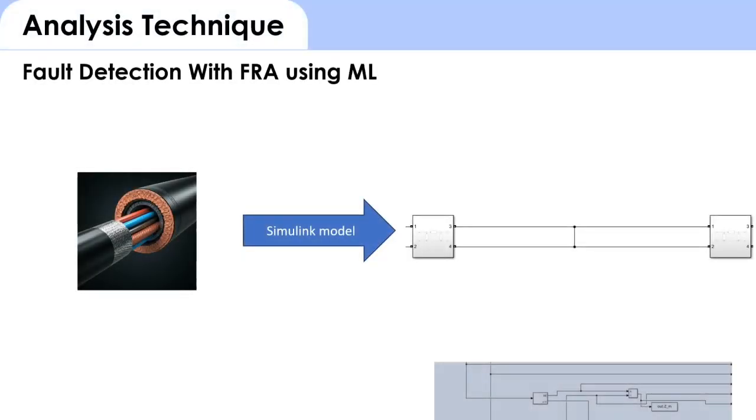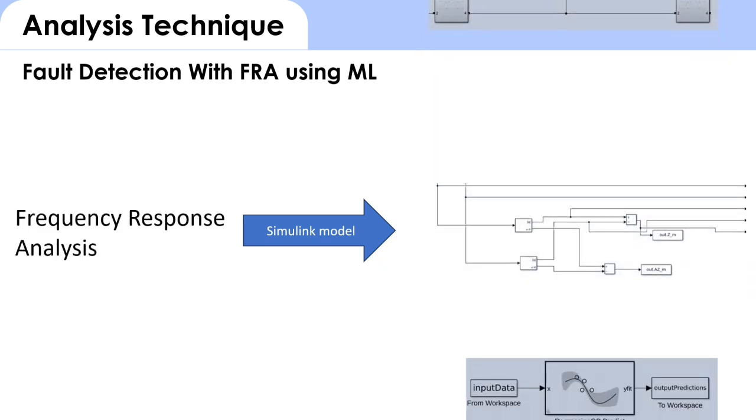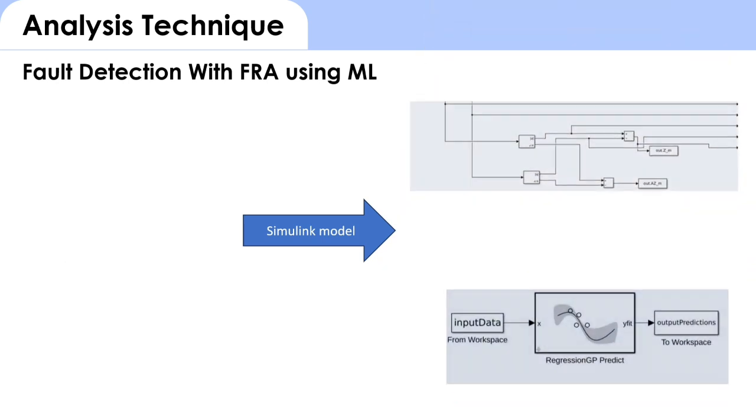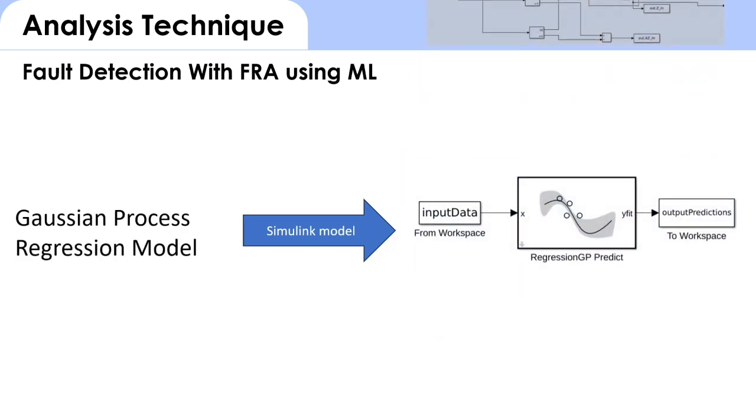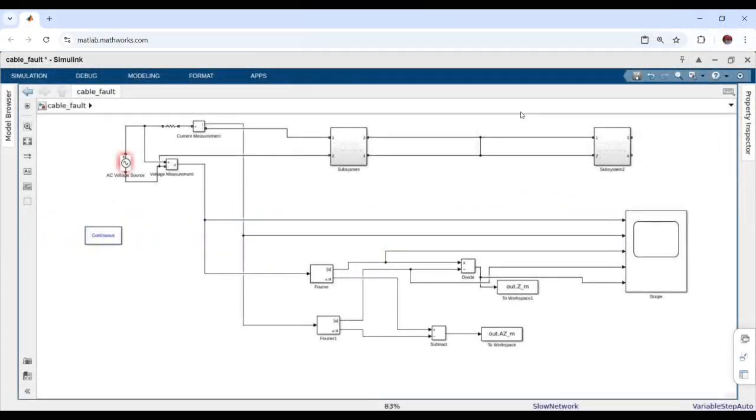Following are the models which I have created using different Simulink blocks for making my simulation successful. This is the model prepared by me, which illustrates the project as follows. The two subsystems are used to demonstrate the 10 km long underground cable, and this short circuit is done so as to get the faulty data from that.